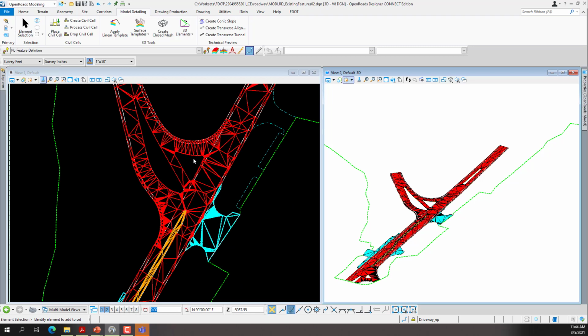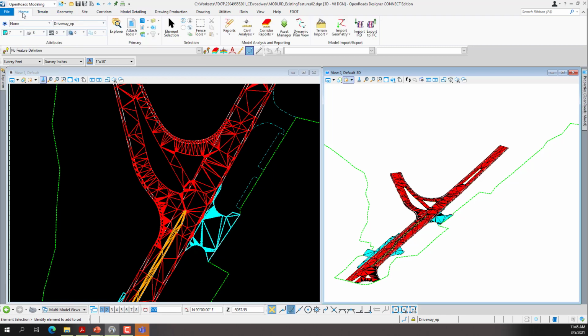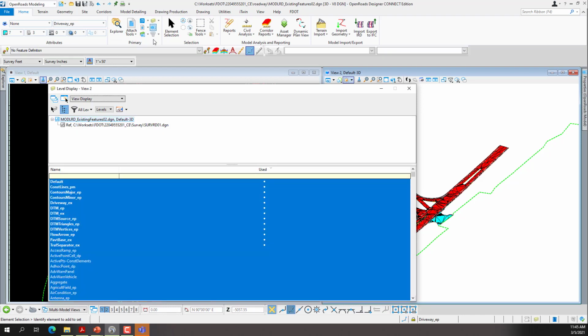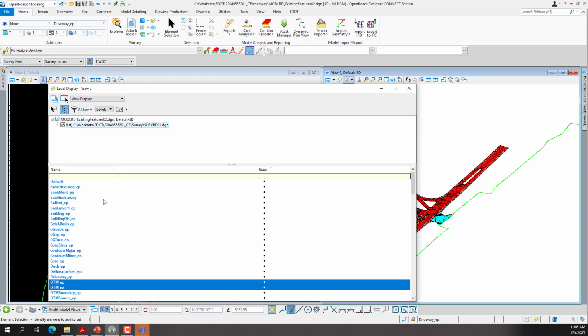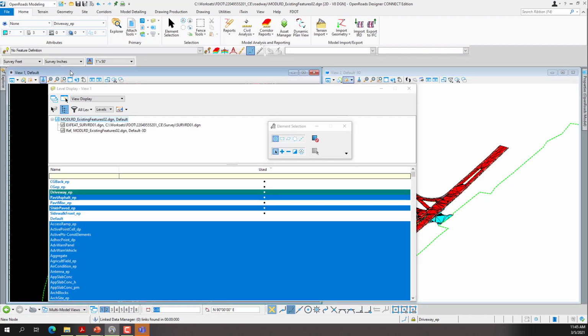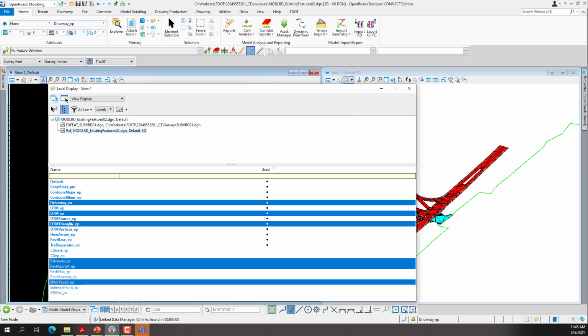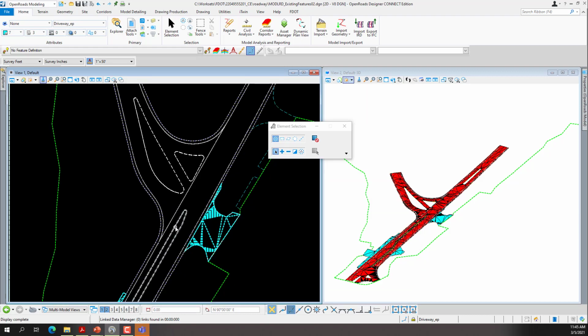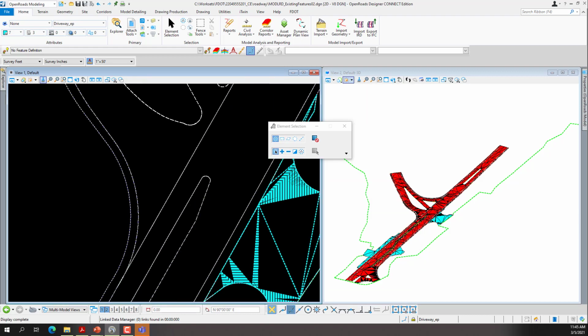and if we need to, we can clear off or turn off so it's easier to see the triangles. So let's go to the Home tab, Level Display. We'll go to our 3D model. We'll make the view active first. So we have different ones. So I want to go to my 3D model, and I'm going to turn off my triangles. We have our pavement asphalt lines.